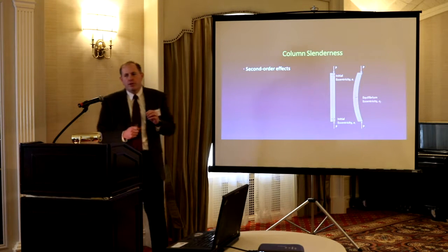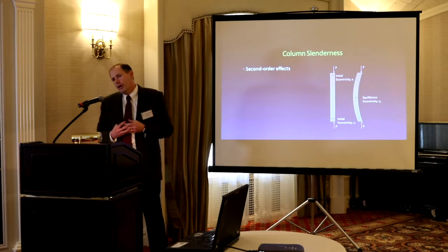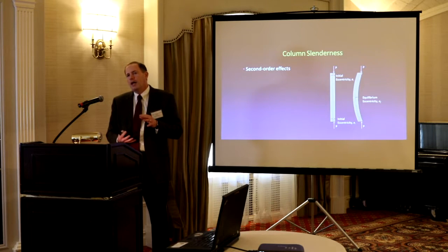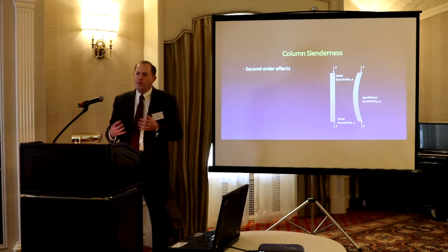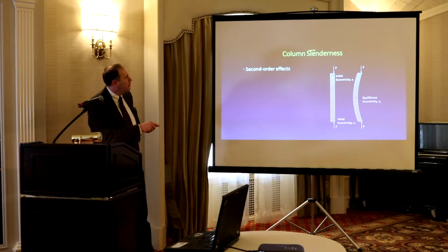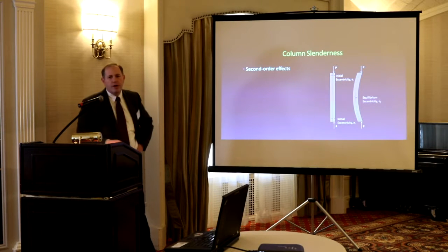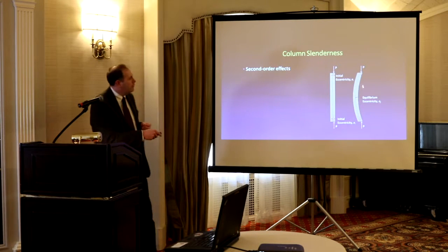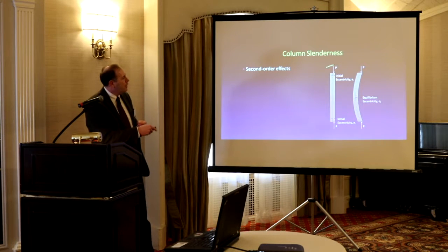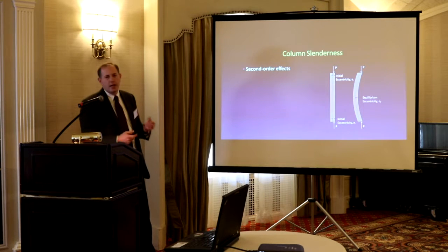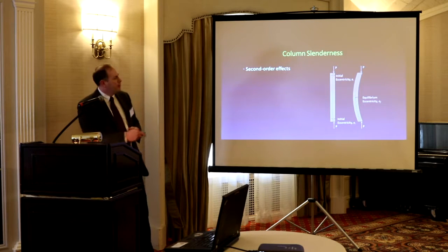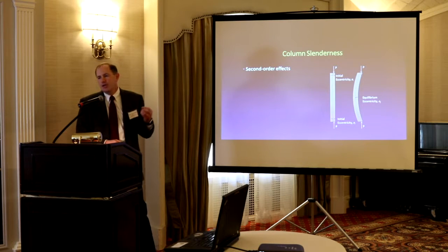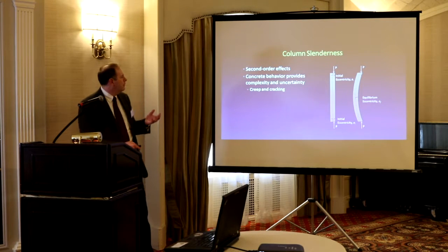Columns, when we generally talk, especially at an undergrad level, we talk about really these short columns or stocky columns because we don't have to worry about one major thing called slenderness or second order effects. The second order effect is additional forces that develop because of the bending of that member. So in a first order, we just look at the forces in this member. But with second order, we have to consider the fact that it's bending, and that bending is going to cause extra forces.